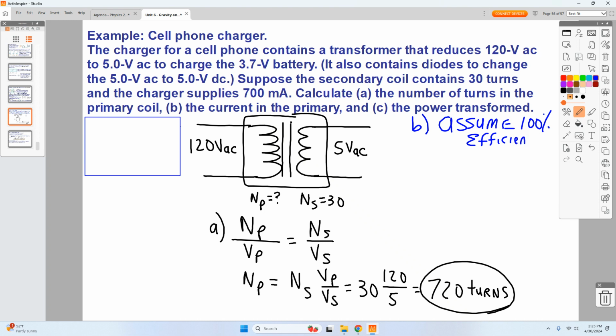These transformers are designed to really be efficient. When I made this thing, its efficiency is about 8%. I mean, it's very poor. So I'm not going to have students build something like this because the efficiency is so low. The people that make transformers actually build them to operate really efficiently. They do that by submerging them in some sort of dielectric material. They make sure that the cores don't have all these sharp edges to them. They're usually either an interwoven kind of thing or a spherical setup. So this is just inefficient.